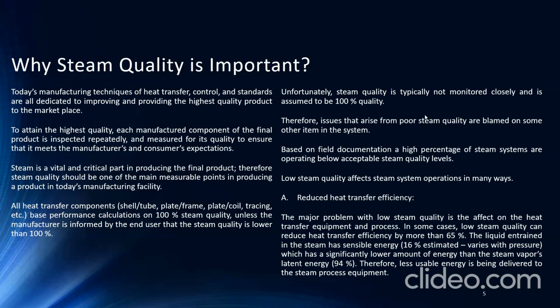Unfortunately, this steam quality is typically not monitored closely and is assumed to be 100%. Therefore, issues that arise from poor steam quality are blamed on some other item in the system. So based on field documentation, a high percentage of steam systems are operating below acceptable steam quality levels. Low steam quality affects steam system operation in many ways.